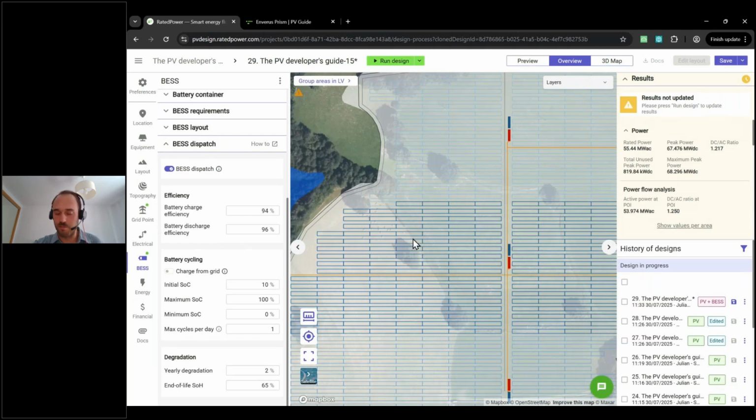We can use our DC power, the power from the PV side, and charge the batteries directly, or if our inverters are clipped. We might have a very sunny day where we have a lot of DC power and our inverters are overloaded. We can use that excess energy and just put it directly into the BESS. So this is how we can peak shave or utilize that energy.